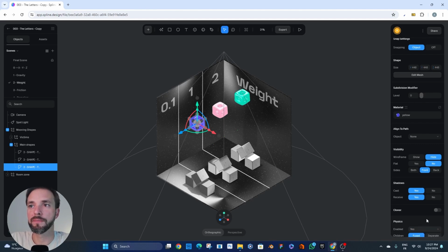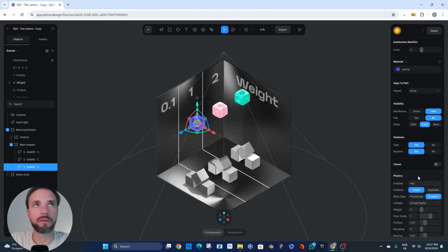If you turn yes, your scene will always calculate the gravity for this element. So if you do that for everything, your computer will calculate everything, and it's not good if you want to put your scene online in a website. It will be too heavy. So, if possible, always turn on based on visibility.